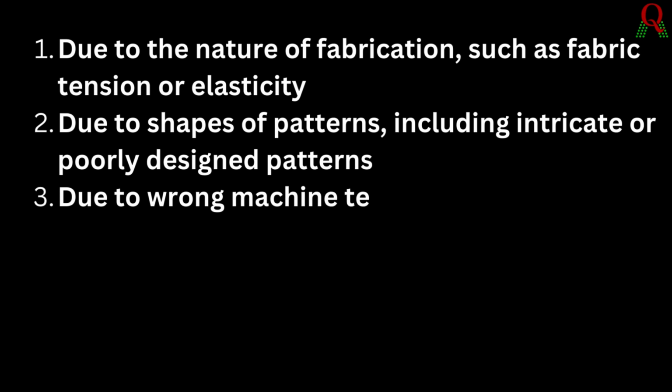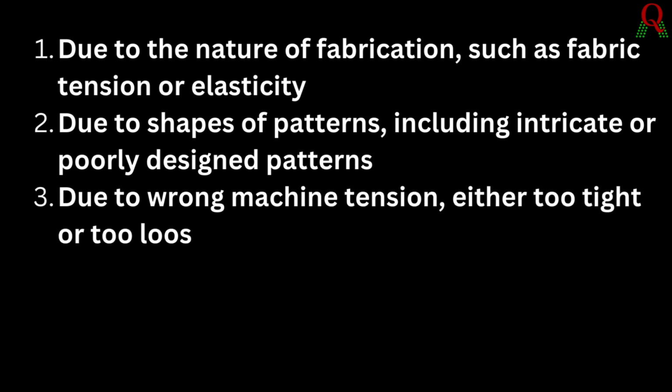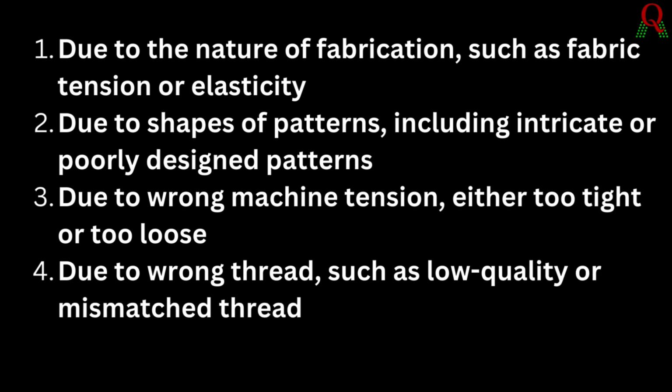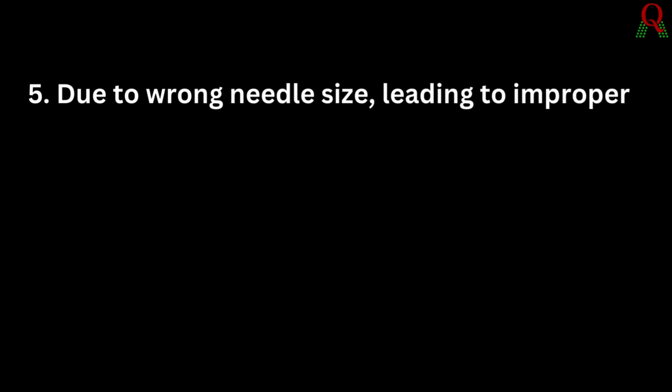Due to wrong machine tension, either too tight or too loose. Due to wrong thread, such as low quality or mismatched thread. Due to wrong needle size, leading to improper stitch formation.